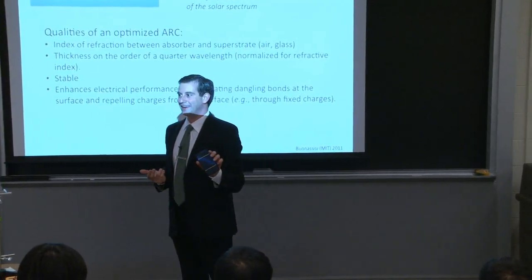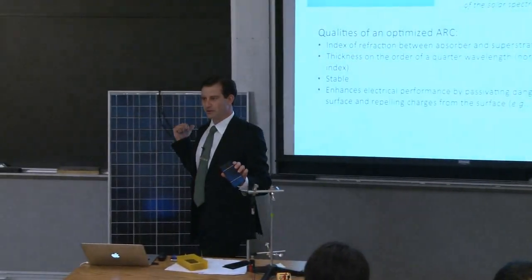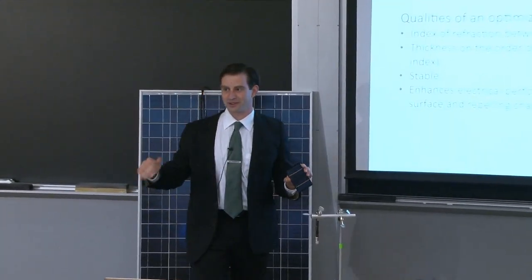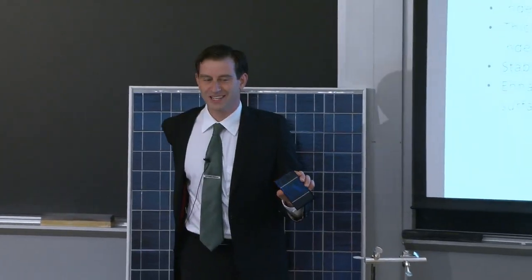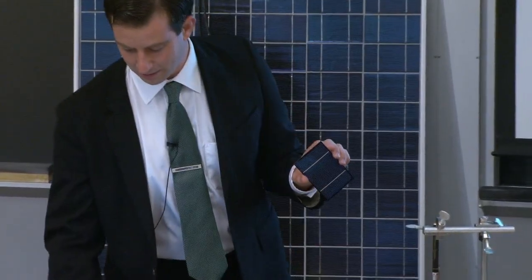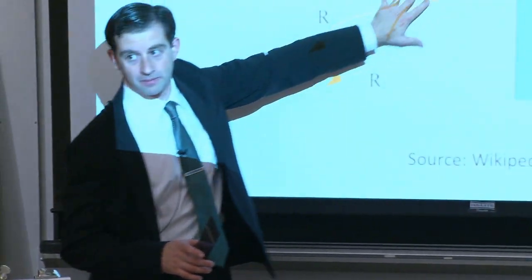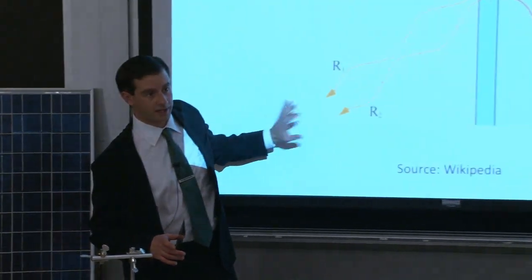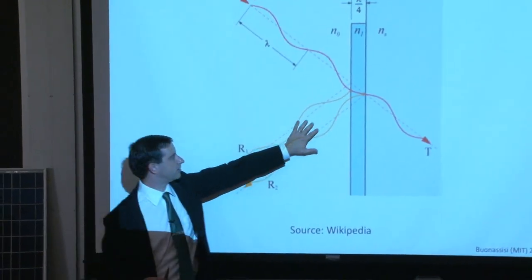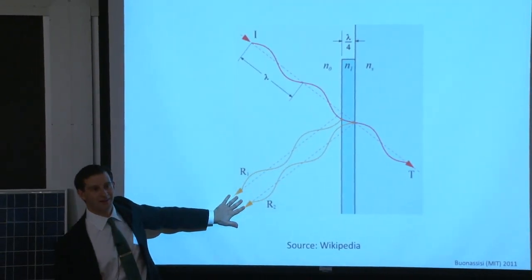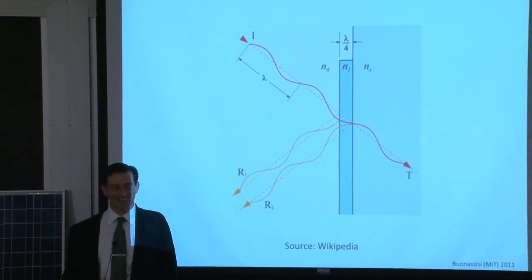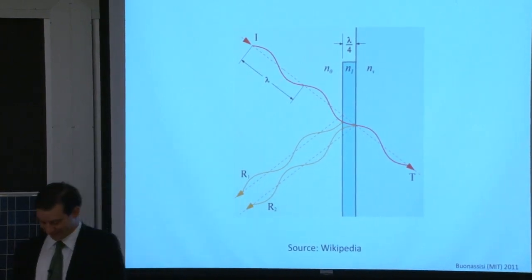That's pretty cool. And it's not absorbing the light. The anti-reflective coating is not absorbing the light, which is really important. We want the solar cell underneath it to be absorbing the light. The anti-reflection coating is enabling the light to be absorbed because it's suppressing the reflectance. The reflected modes at that particular wavelength are suppressed because of the destructive interference. That's cool. I really get a kick out of anti-reflective coatings.